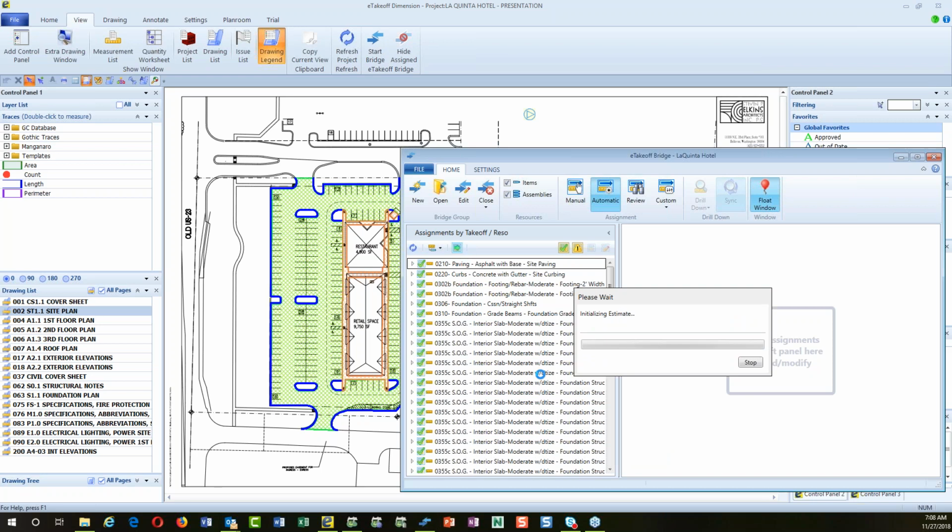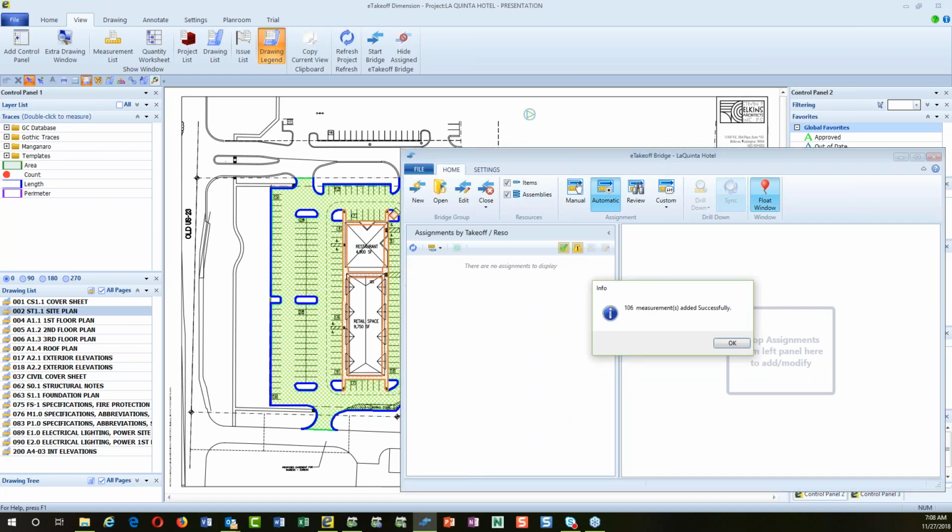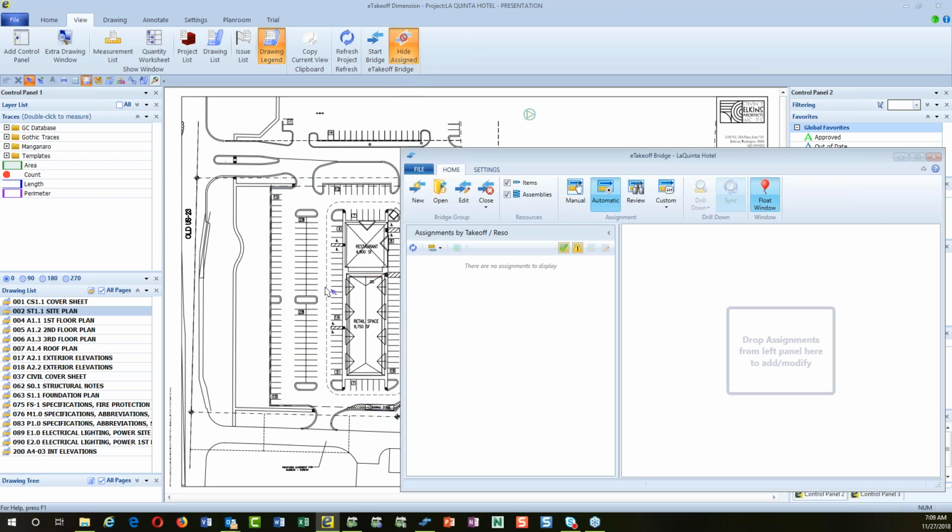So I'm going to go ahead and just send all these to the estimate to create an estimate. All the pages that we've done takeoffs on here are all being filled out with all of my items from each takeoff, and then they'll be transferred over into my estimate. Once I'm done with my estimate, you'll see there will be a dynamic link with every item that we've taken off in this drawing on this project and every line item in my estimate. That'll come in handy when we need to make some changes. So I can actually hide everything that I've sent over, and when I do that, everything will disappear that's been sent over. I can show what I've got, but I can also hide them to see that they've come over. So we'll just go ahead and hide those.